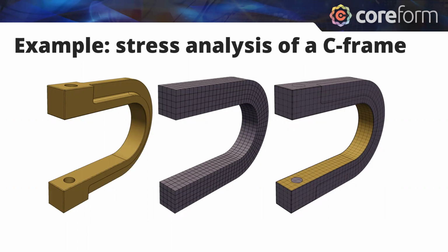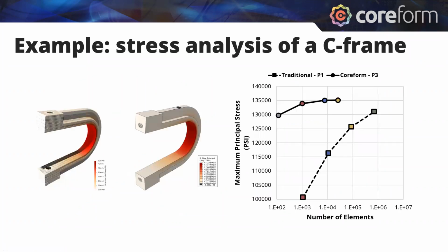So we just immerse this in an object domain that captures the major features of this geometry, but immerses all of these fine details, which is then a very rapid process, and it's not challenging to build a hex mesh on this at all. And then we can compare this to traditional finite elements, where we're basing this on traditional nonlinear analyses that use linear hexes.